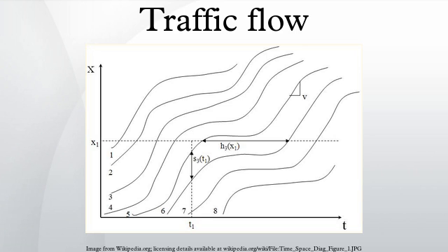Now, suppose that at a certain location X0, the highway narrows to one lane. The maximum capacity is now limited to D, or half of Q, since only one lane of the two is available. D shares the same flow rate as state D, but its vehicular density is higher.